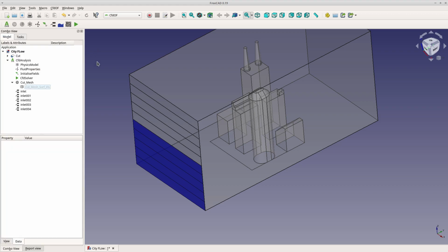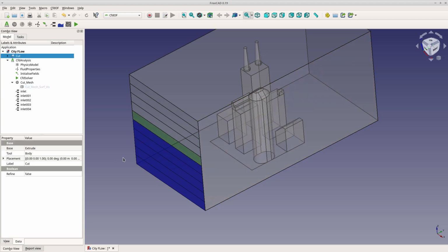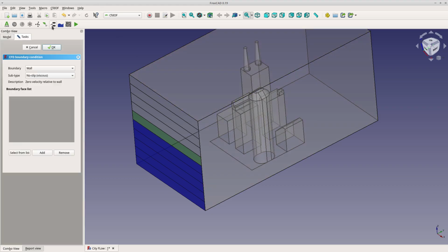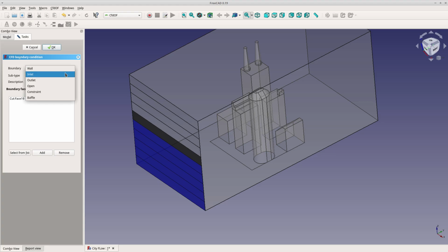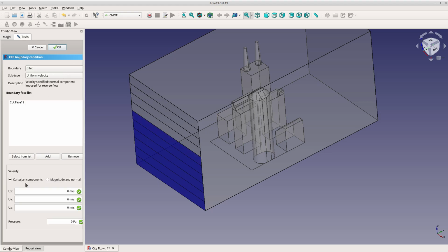But also we may need to do some fancy thermodynamics and make sure that if it matters to us, we would drop the pressure as the fluid accelerates, because you would see pressure changes in a moving fluid. So it depends on just what kind of resolution you need. And if you're going to do flow analysis, you really need to have thermodynamics knowledge if you're going to go super technical with it.